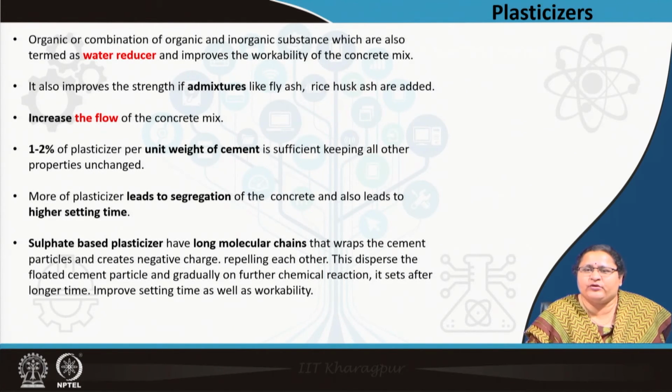You have transported concrete for large scale sites, you may have transported concrete from some ready mix agent. So, they are already brought to you maybe with a delay. So, sometimes you may require your concrete to remain unset for a longer period. There comes the role of plasticizers. They are also referred to as water reducers.